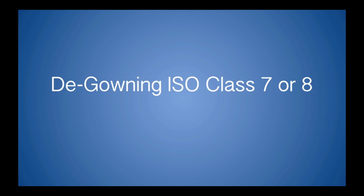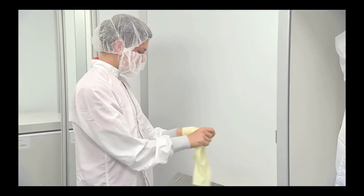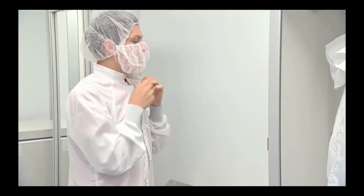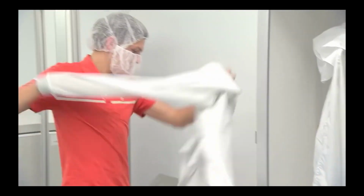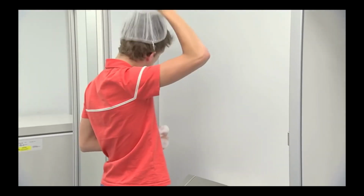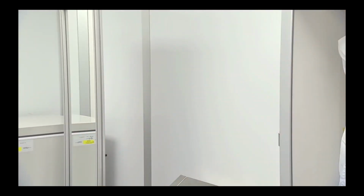Here is the degowning process for an ISO 7 or 8 cleanroom. Take off your gloves and dispose of them in the proper receptacle. Remove your smock. If you are leaving the cleanroom for a short period of time, you can hang your smock in the gown cabinet. If not, place your smock in the hamper so that it may be washed and reused. Remove the face mask and bouffant cap and dispose of them as well. Finally, exit the cleanroom, take off your booties, and throw them away.